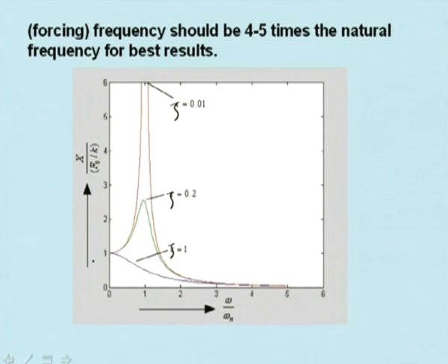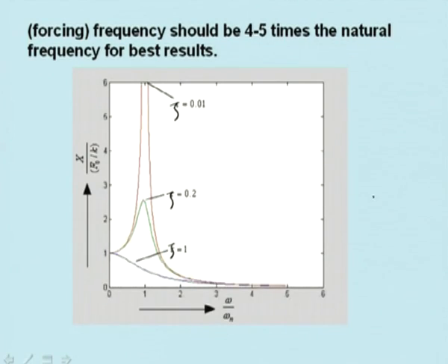But if we apply a very high frequency, then the displacement approaches 0. Why? Because the mass is not able to respond because of the dashpot, it is not able to move at all.